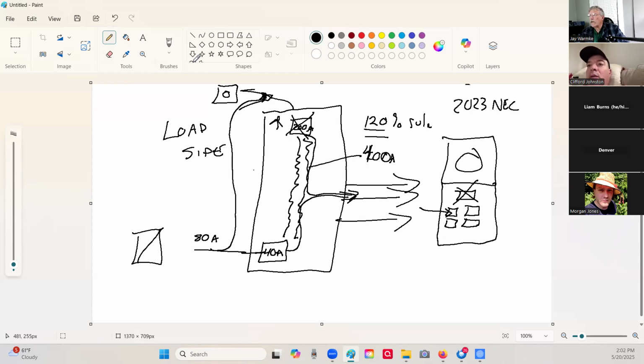And you don't have to worry about the old existing wire. I've seen them. The new ones have a little label, and it even says solar on it. It's crazy. Yeah. Well, it's required for new construction if you're following the NEC, but it's also required in many jurisdictions. You've got to upgrade to the newest code if you're doing substantial changes to your electrical system in the house. Well, installing solar, the inspector may determine that's a substantial change.